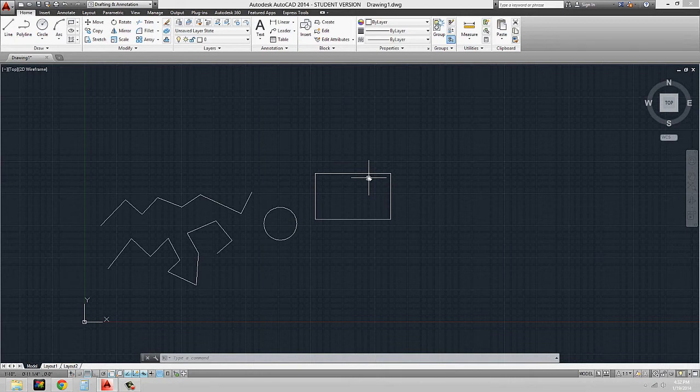Now, yes, theoretically you are drawing with infinite space, but AutoCAD also imposes drawing limits on each file and will limit the viewing area for your drawing in model space. So you can set up the limits by using, there's a limits command, okay, that you can use in order to set up those limits. But honestly, the way that I use it is I just zoom to the extents, okay, of the model space. And what that does is it zooms to the extents of the objects. And what that does is I find that it just tends to break those limits anyways.